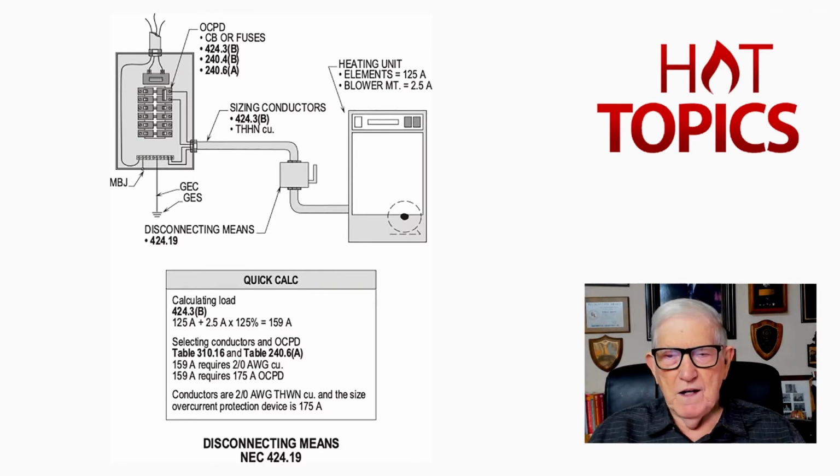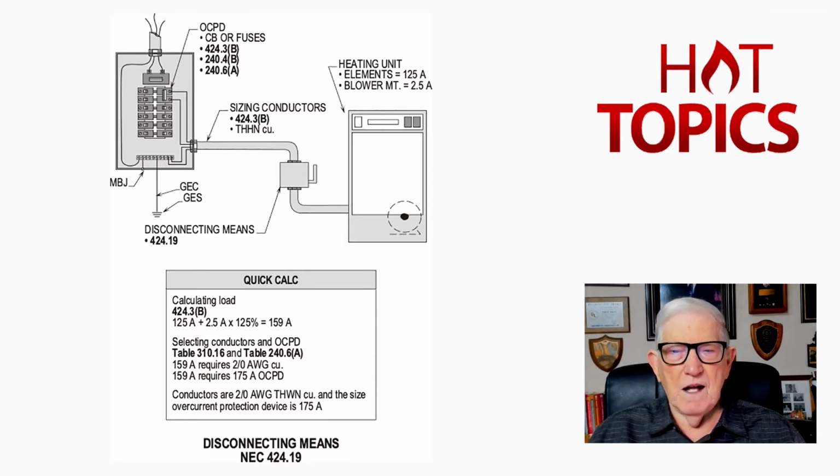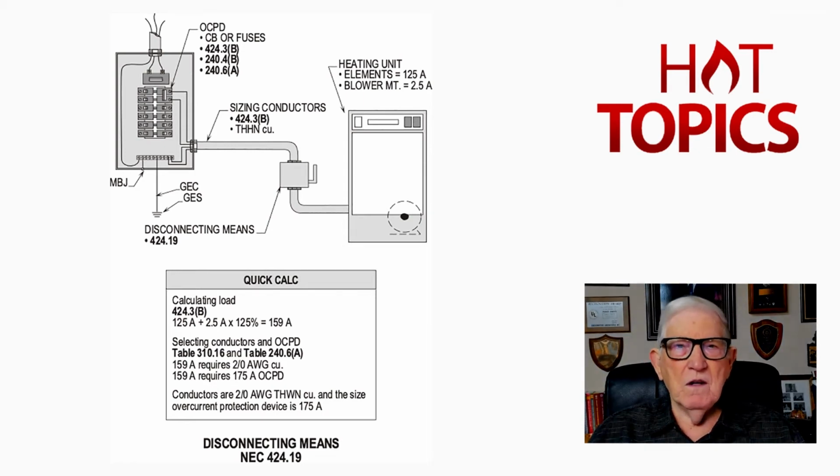In other words, we're going to have to connect it to the 75-degree column for your THWN copper conductors. And again, that's in accordance with 110.14(C)(1)(a) for our terminations and a load of this capacity. And you say, well, now, isn't that 100 amps or less if I should use 110.14(C)(1)(a)?